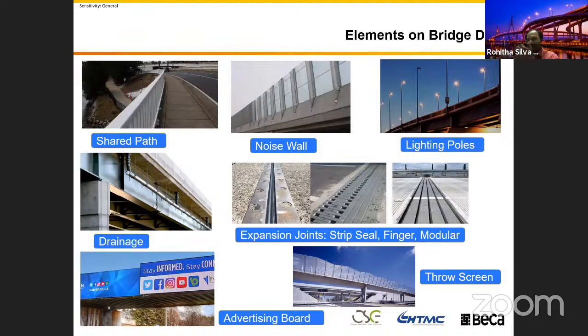Main elements in the bridge are the bridge girders, the bridge deck, and the bridge barriers. These are the three main elements, but all the other elements are part of the bridge we need for functionality requirements. We need all these small elements in there, but in terms of bridge design, the main thing you are designing is these three elements. The rest is assembling. They are the miscellaneous structures you're going to design.